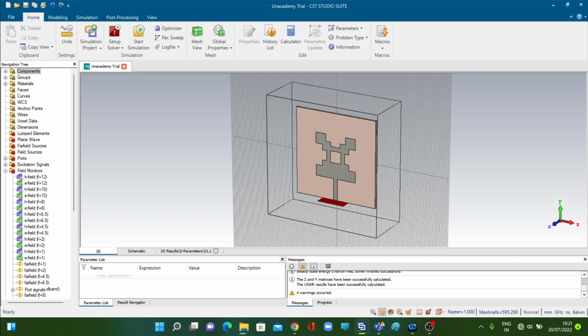So we started by implementing this Hilbert fractal on the top edge, which you see here, the right edge, which you see here, and this left edge. Okay. And we went up to the second order iteration of the Hilbert fractal. That means we cut two slots in succession. And of course, we can go on by adding different iteration steps.